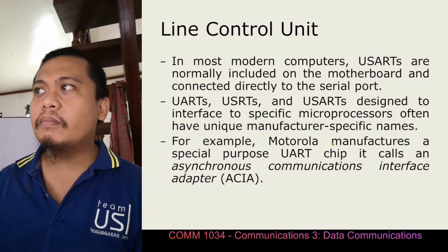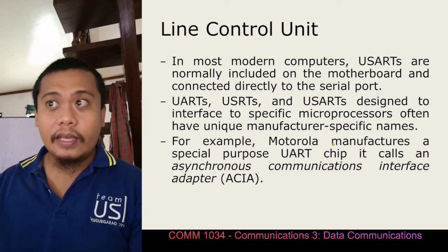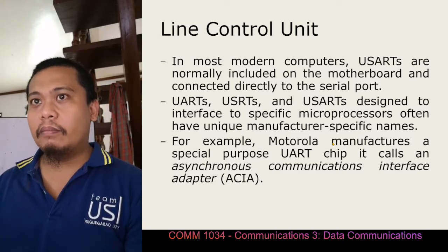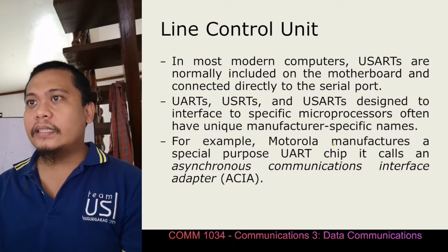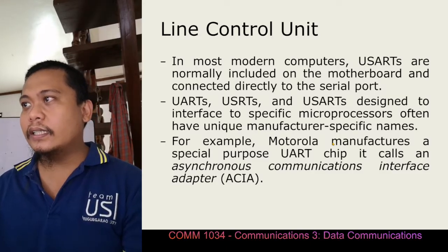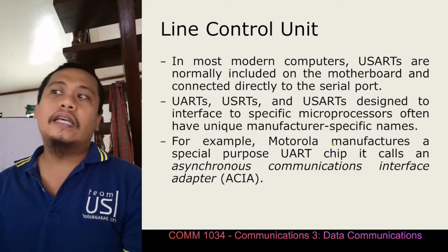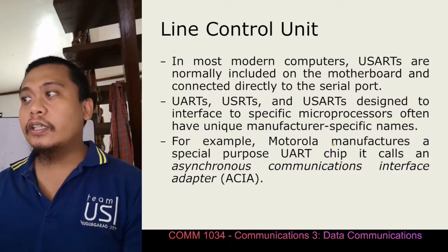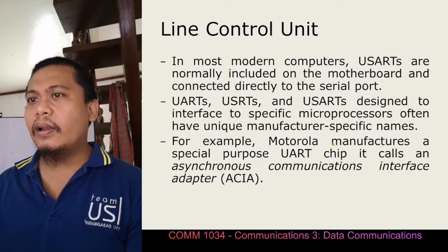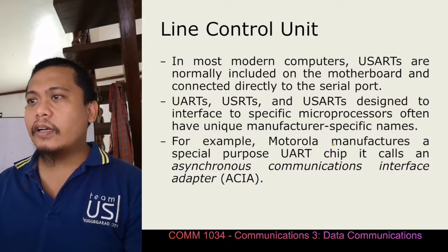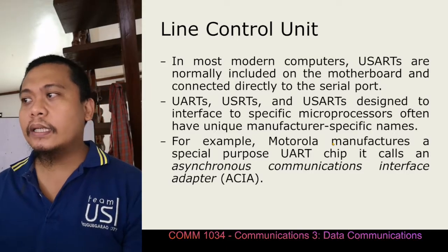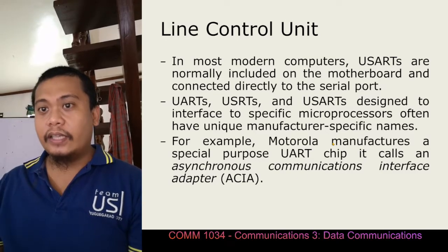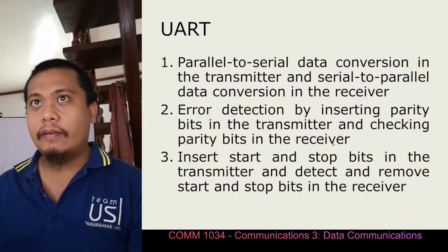In most modern computers, UARTs are normally included on the motherboard and connected directly to the serial port. UARTs, USRTs, and USARTs designed to interface specific microprocessors often have unique manufacturer-specific names. For example, Motorola manufactures a special purpose UART chip it calls an Asynchronous Communication Interface Adapter, or ACIA.